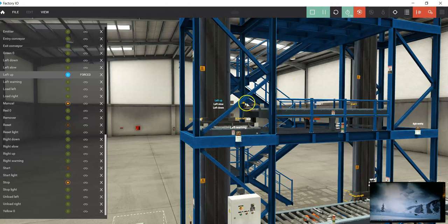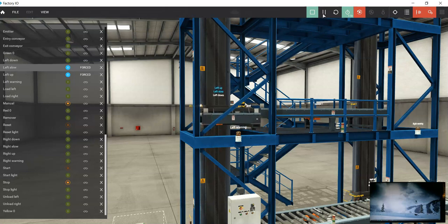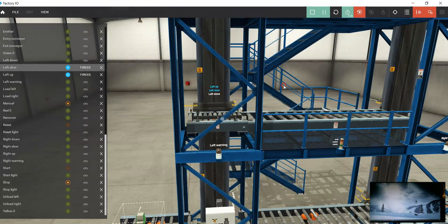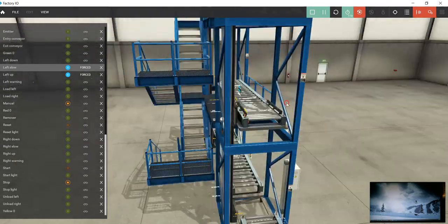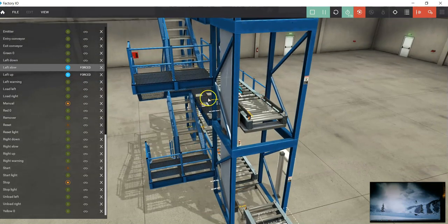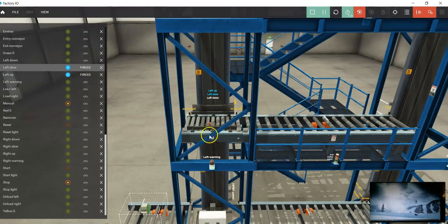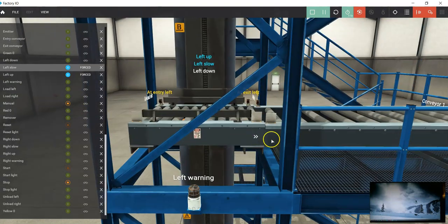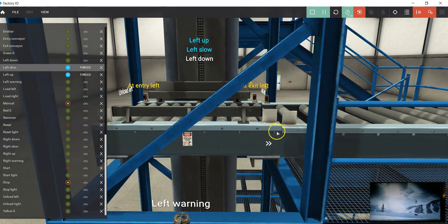When you get close to this position, you also have to turn on lift slow, and then it slows down, and then when both those signals turn on, which is right about here, I think I missed it a little bit. But let's see. Okay, so I got the high position, but I missed the low position, and you can see it right here because I was manually doing it, they aren't even.